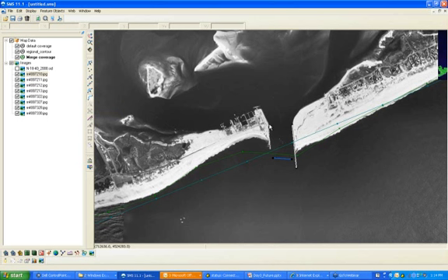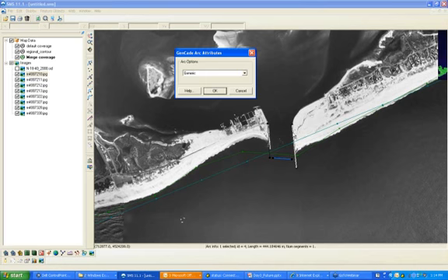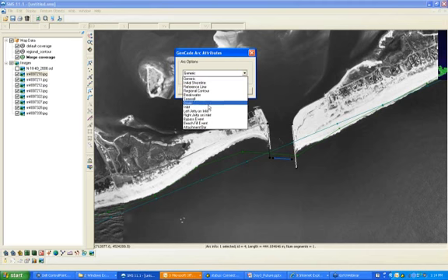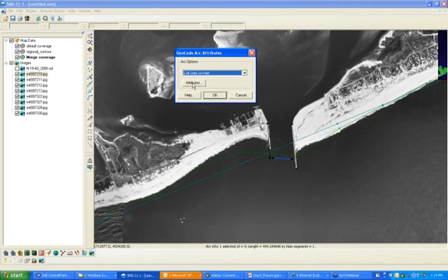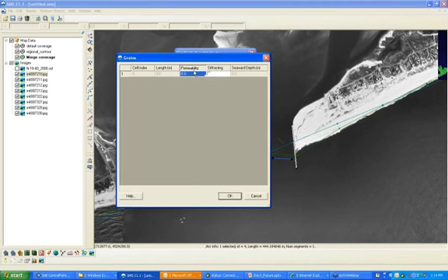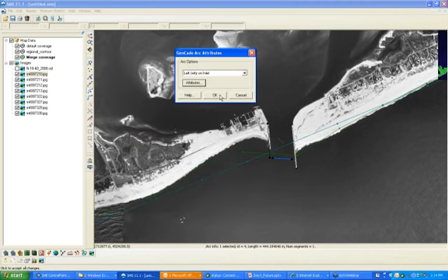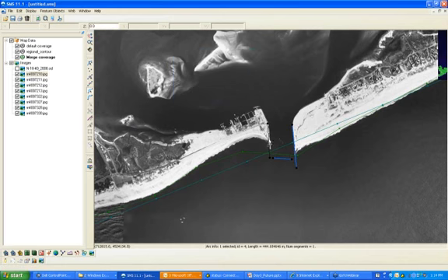I'm going to do the same thing for the right. And then I'm going to go to Select Feature Arc. I'm going to double click. I'm going to name this my left jetty on inlet. Go to my attributes, and then I'm going to define them here. The permeability is 0. It is diffracting. And we're going to say the seaward depth is 3 meters. And then we're going to do the same with the right jetty.